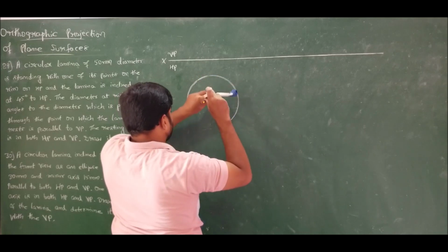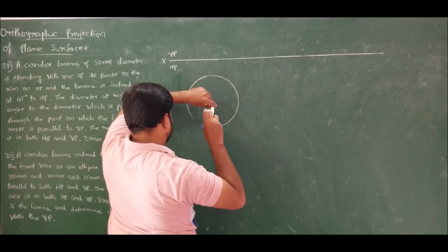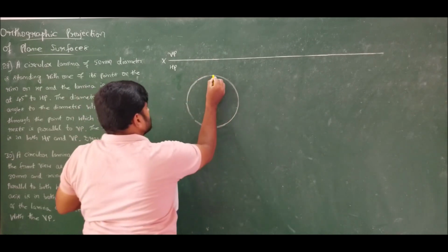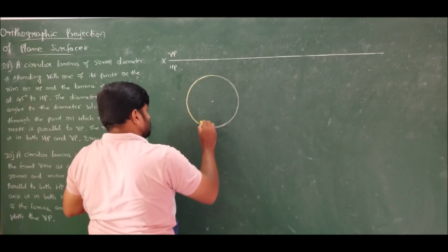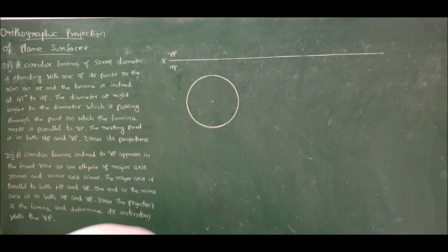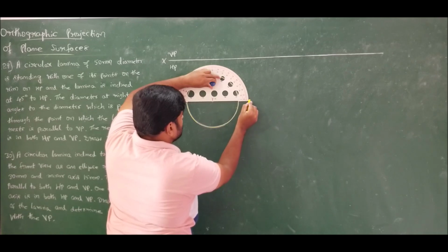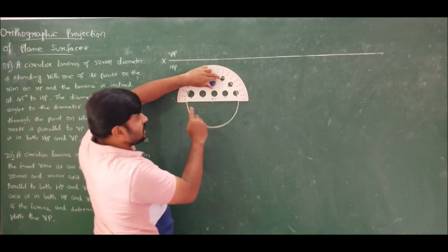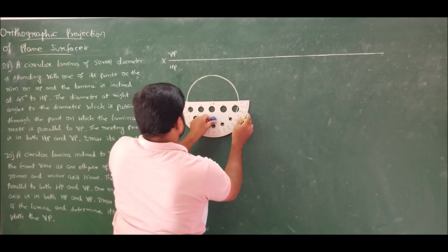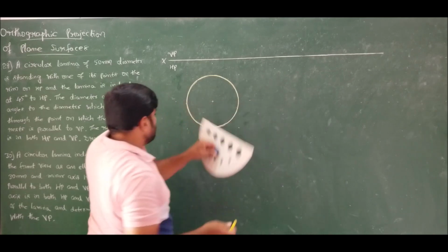So a radius of 25 is measured and the circle has been drawn. So we have drawn a circle of radius 25 mm. Now as I said, divide this into 8 equal parts. You can also draw it by dividing into 16. Let me do it with 8 equal divisions on the circumference by taking 45 degrees, 45, 90, 135, 180. So similarly we have minus 45, minus 90, minus 135, minus 180.